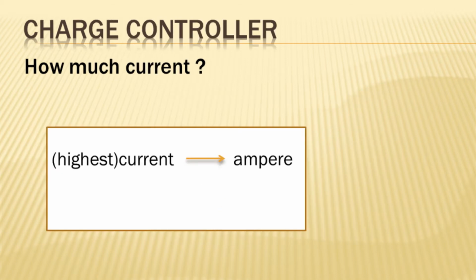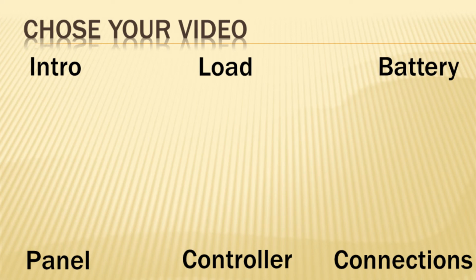Charge controller, how much current can it handle? And here we always need to consider the highest current that can occur in the specific system we are designing in amp. And finally, this is the overview screen that you will see at the end of each video,